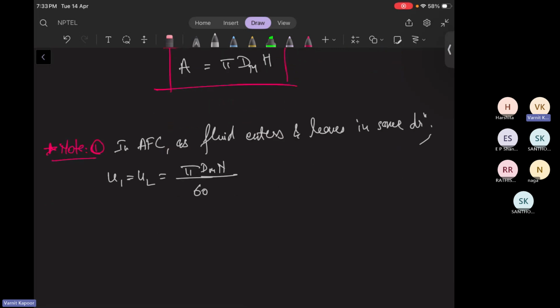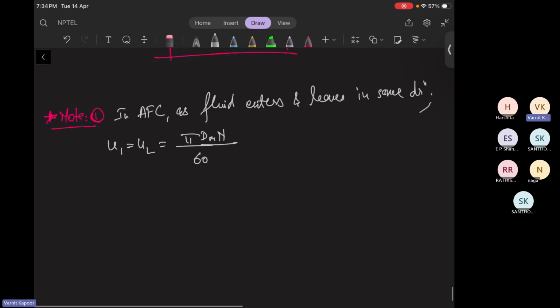For design consideration, we say that we have zero axial thrust on the bearings. That means the velocity of flow at the inlet is equal to the outlet. Again, I'm talking about the radial blade scenario. There is no whirl component, so there will be no thrust.